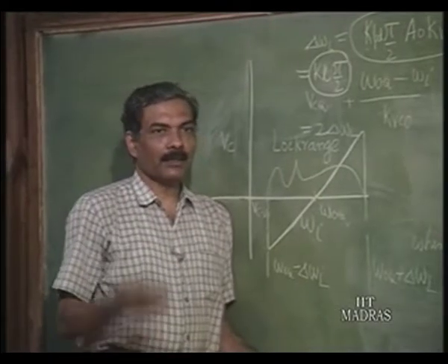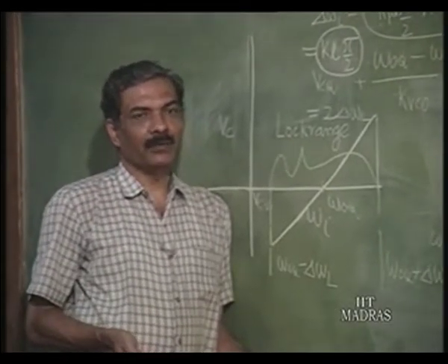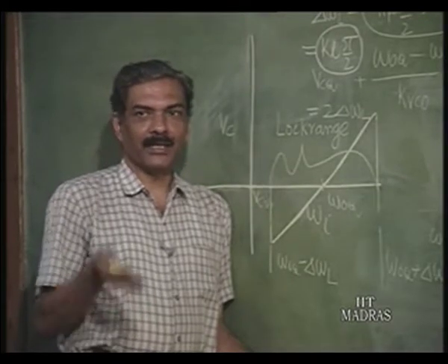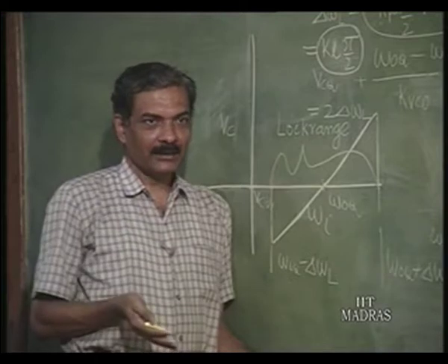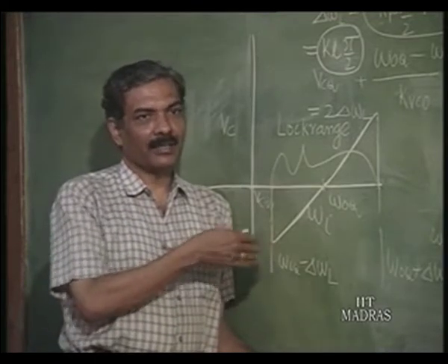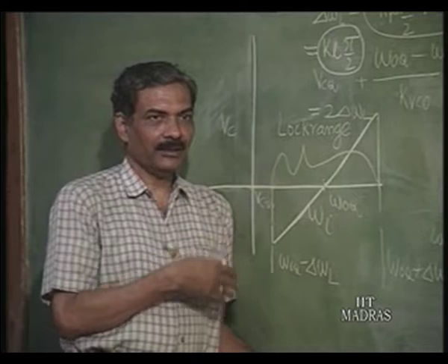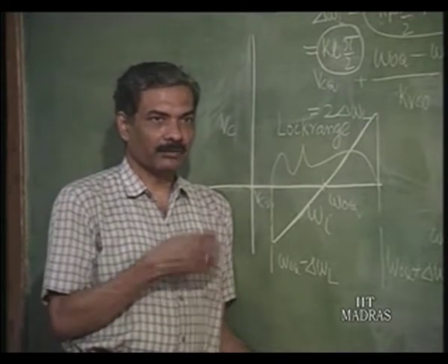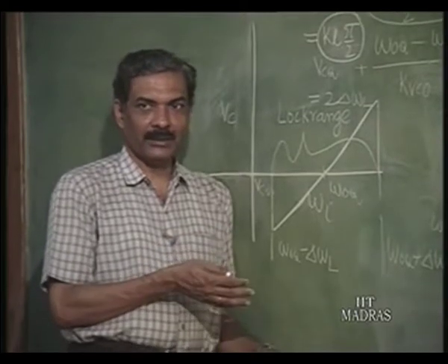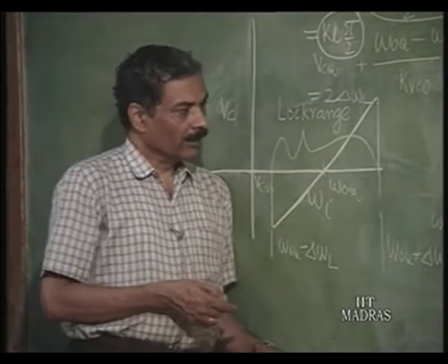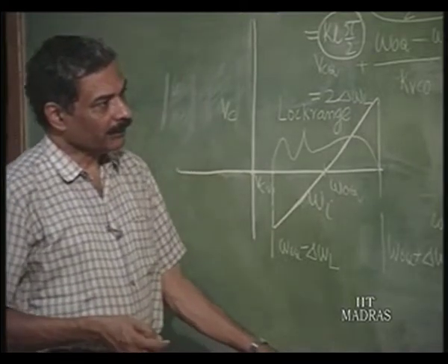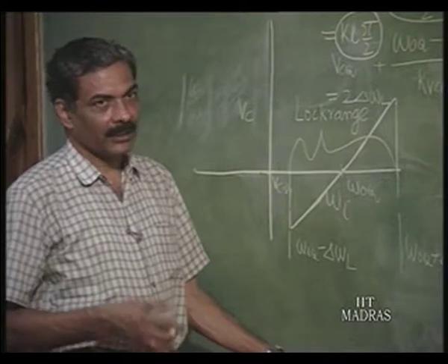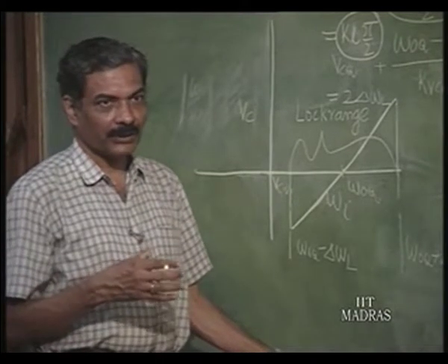This is like our limit for the output voltage of the op amp, which can go almost up to the power supply. Like that, there is this dynamic range limitation for the phase lock loop. It goes out of lock beyond this, and is not going to be kept in lock. If you have understood this, then we will also try to understand another important concept associated with the phase lock loop.